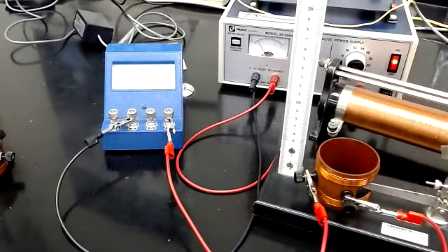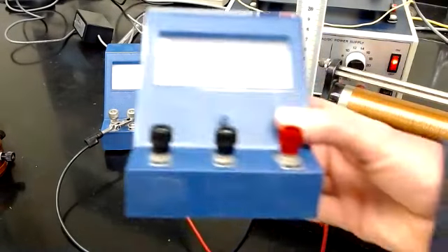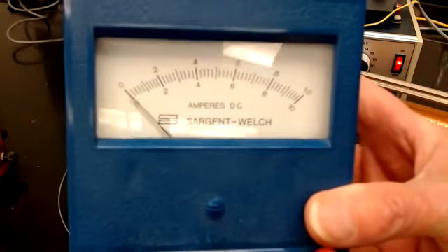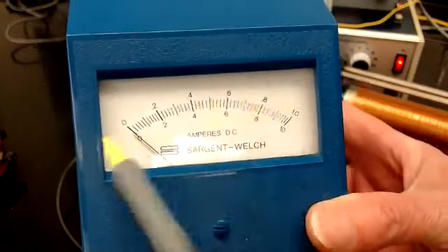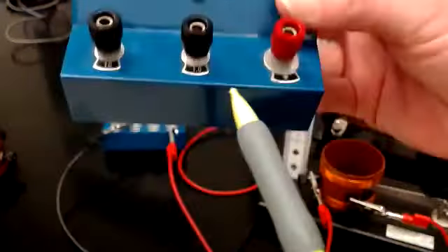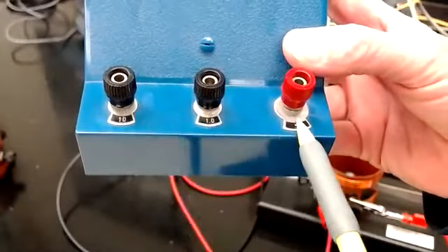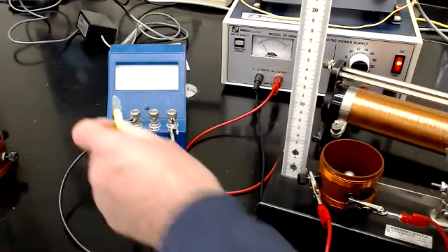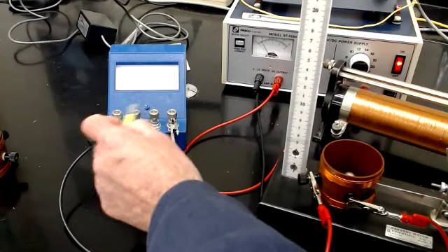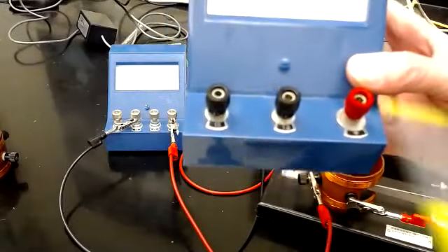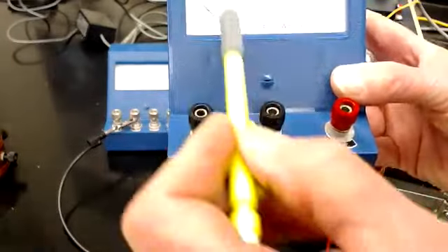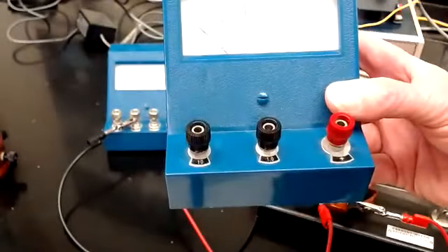Now these meters, let me hold one up here. Okay, they have a couple of different scales to them, and they have different inputs. Like I said, there's one marked positive, like this one here, it goes to the positive pole, and the other, you have your choice from the others going to the negative pole, and those choices tell you which scale you're going to be reading on.